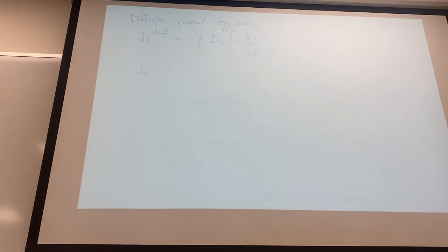And conversely, diffusion of p-type, D sub p, the p-type diffusivity, times partial p, partial x. This thing is the diffusivity in centimeters squared per second. I think this is sometimes called the Einstein diffusion equation, even though I think 3 people independently discovered it at the same time.